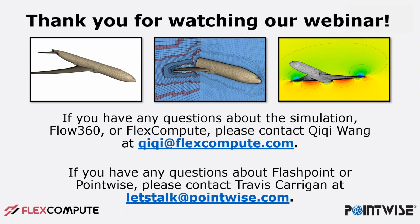You can have a large mesh, but a steady state simulation actually finishes faster than some of the unsteady simulations, even with a smaller mesh. And if you are looking at something with a very long time scale, you may have to integrate for many time steps. That usually takes far longer.